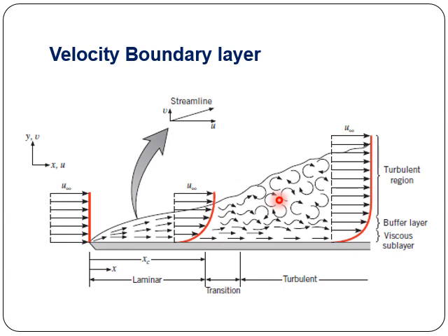The mixing will be from one layer to another, because of which the velocity drops, and because of this, the point at which you get 99% of the free stream velocity is much farther away from the surface. So the thickness of the boundary layer will increase with the increase in turbulence.